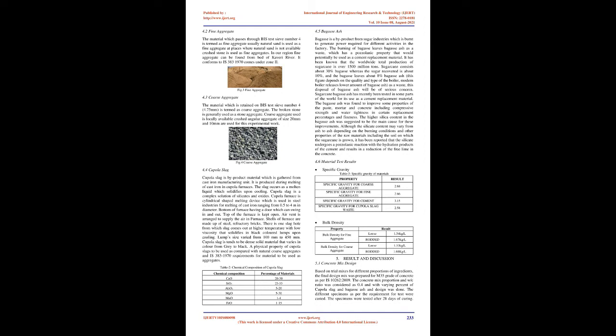M. Vijayasekar Reddy and I.V. Ramana Reddy studied the behavior of high-performance concrete, which is the most used type of concrete in the construction industry. They replaced cement with supplementary cementing materials like fly ash, silica fume, and metakaolin. With 6% replacement of sugarcane bagasse ash, compressive strength increases 9.67% compared to normal concrete after 28 days of curing. The mix design adopted was M60. Cubes were cast and cured.